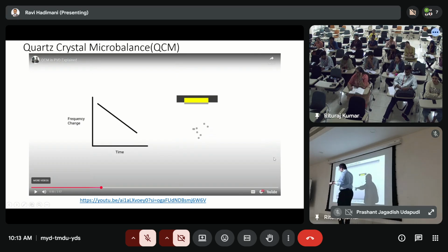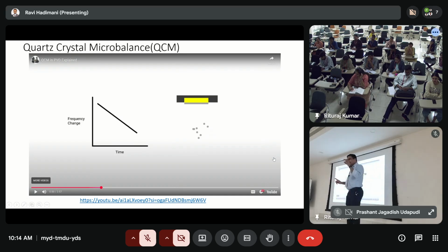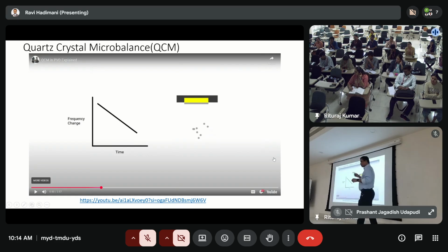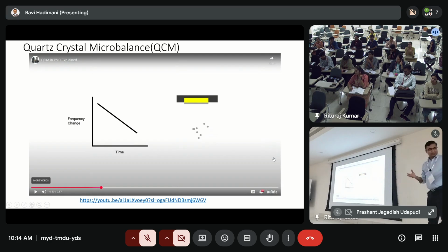That's monitored by this. So we literally keep looking at it, and if it is thermal evaporation, the curve is going really fast, and we target, say, I need only 100 nanometers. And when it hits 80 nanometers, we press it, and then it goes to 90, 95. But if we press at 90, it overshoots. So it's really indispensable. It's a very convenient way to do it. Otherwise, what do you do to determine the thickness of the film? How do you know it's 100 nanometers?